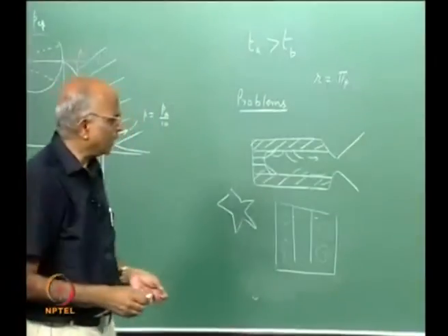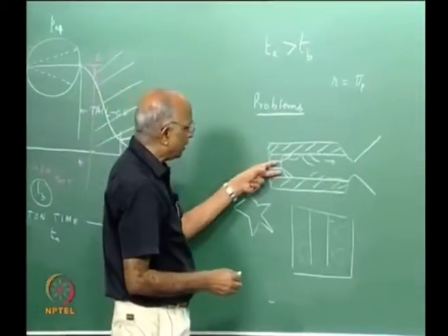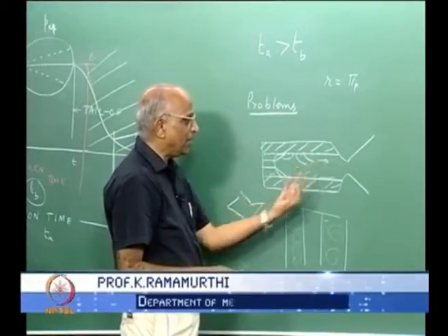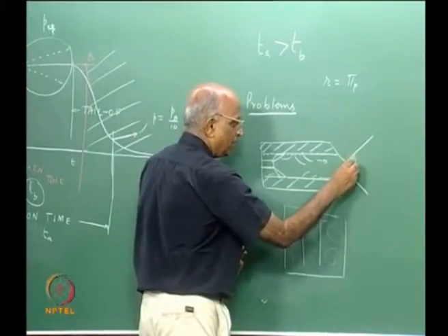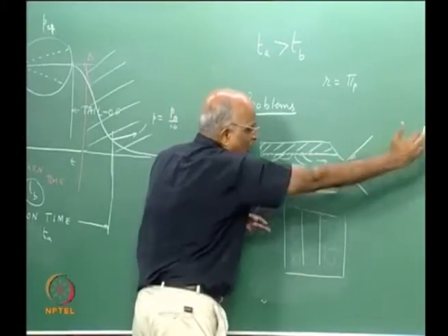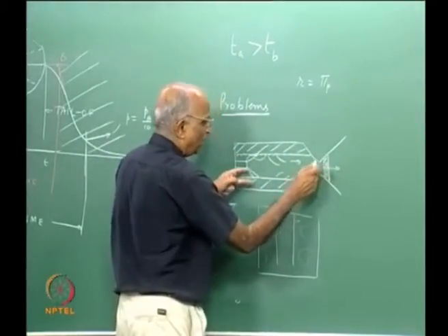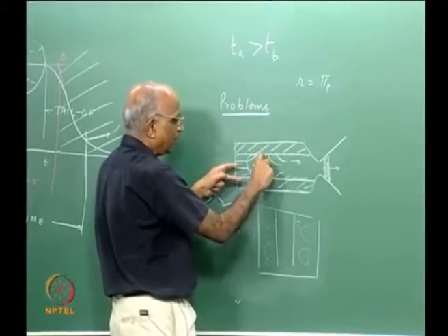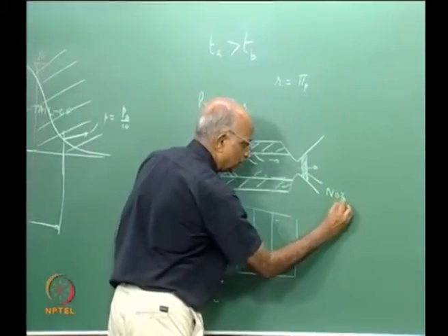Something which I missed out telling when we talked of igniters was, very often when we ignite a motor, the gases are going out, and some of these motors have to ignite in vacuum, and therefore we put something like a closure here. We initially close it like this, and when pressure builds up this goes off, and once the motor is ignited this gets thrown out. Let us make sure that this is around 5 bar to 6 bar such that some minimal pressure gets created. This is known as a nozzle closure.